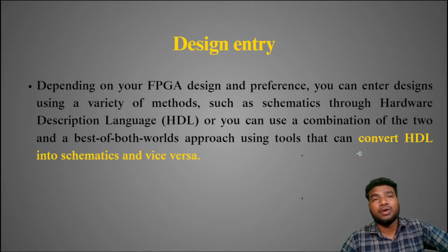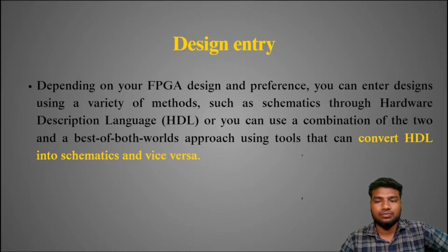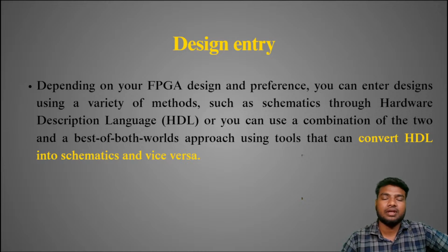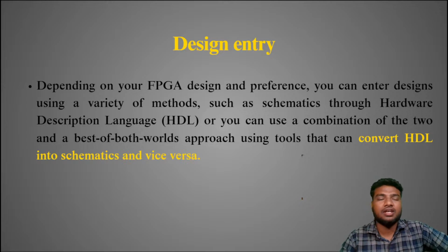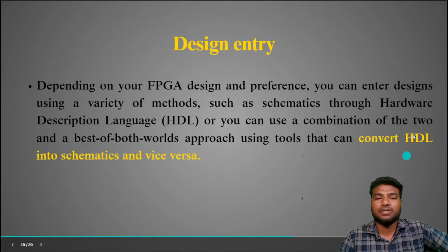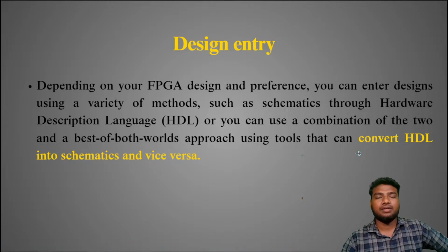There is another way to do design entry: we can convert the schematic to RTL. So that's two things. We can convert RTL to schematic, and we can also do schematic to RTL. We can do both in tools like Xilinx Vivado and Intel Quartus Prime. In this master class we are going to use only RTL to schematics. We will use Verilog code and convert it into schematics in the tool, Intel Quartus Prime. We'll see this in the upcoming sessions.